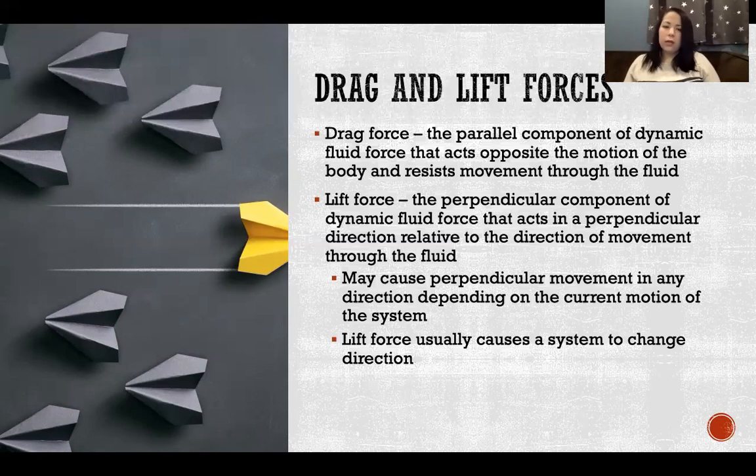So lift force, although it's called lift force, could have a downward action or an upward action, not only an upward action. It depends on the direction of the movement. Okay, so if we're moving at an upward angle or moving at a downward angle, that is going to change the direction of the perpendicular components. That's going to change the direction of the lift force to be in an upward or a downward direction.